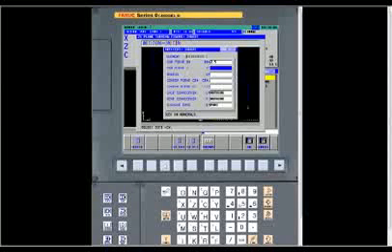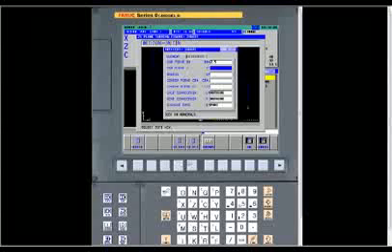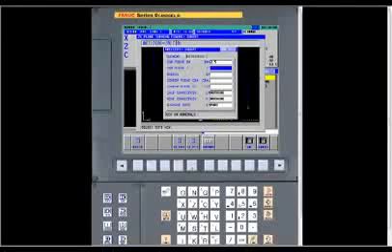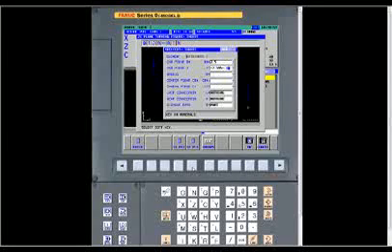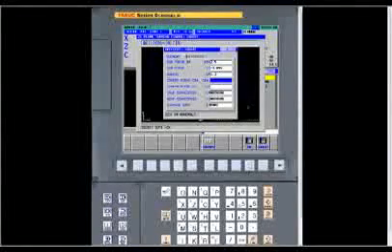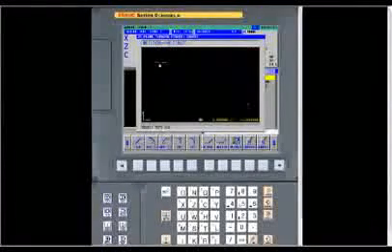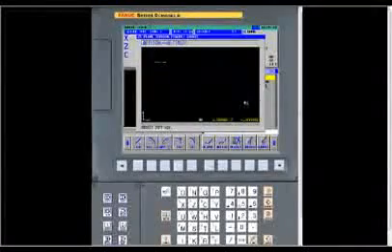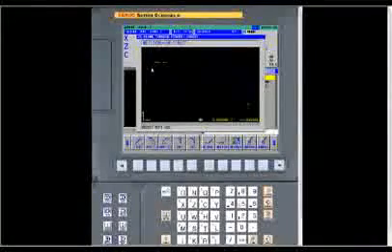And then I don't remember where I told it to go in Z, but if we press this starting point minus incremental, it remembers where we are. So I want to go another 0.5. Enter that. So now it knows where it is. And we'll say it's a 1.5, a 1.3 radius. Enter that, and then say OK. See, it draws the radius. So now we've described the entire profile of what we want to do.